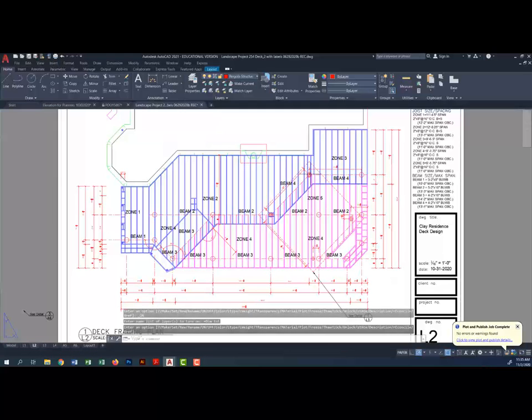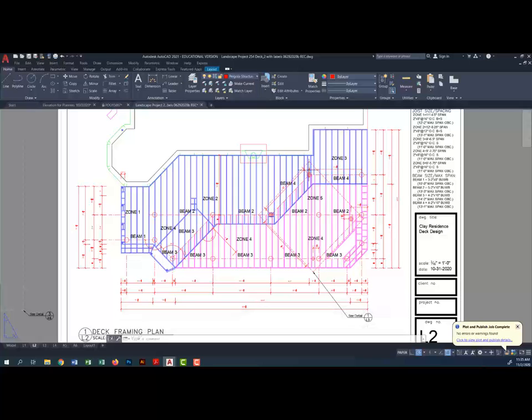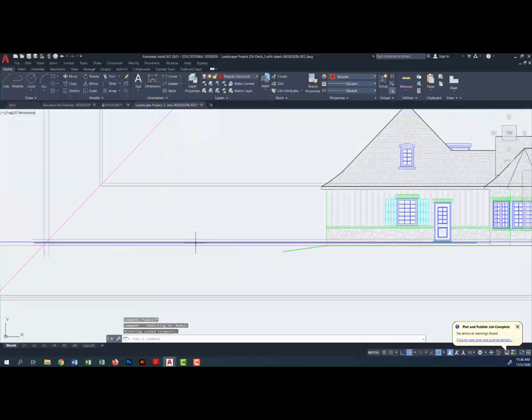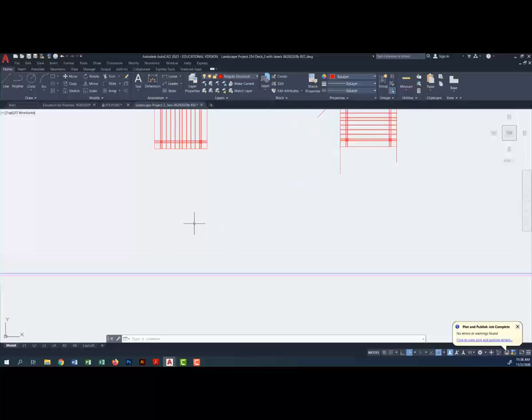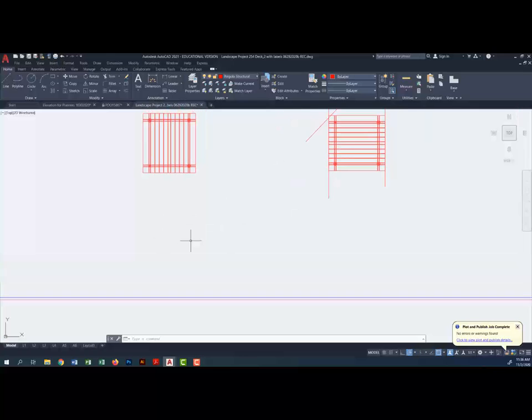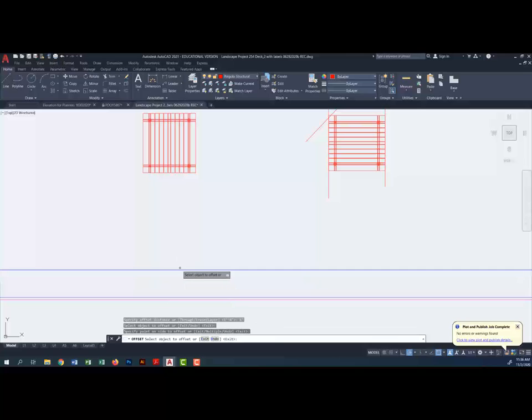And you can see that part of my pergola is on the upper deck, the blue deck, and part of it's on the lower. I want my pergola to have a clear 8 feet between the upper deck, the higher one, and the actual lintel. So I'm going to go back in the model space, and there are my two lines, my upper deck, my lower deck. And I've used construction lines so they continue right across this whole project. And from here, I'm going to now draw the elevation. So I'm going to use offset and 8 feet. And you can make it 8, 9, 10 starts getting a bit high. And there is my height between the blue line, and the blue line is 8 feet.